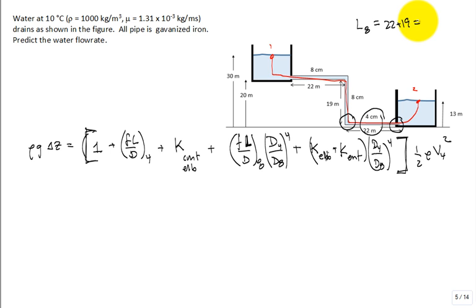Now, what your intuition may be saying, well, I have water in a pipe, and maybe if it's horizontal, I have some air at the top. No, these pipes are full of water, and they're flowing with a turbulent velocity profile. I could see where somebody is like, hold it, something's got to be different. Well, when you're going down, you're changing elevation. Horizontal doesn't change elevation, but that's accounted for in this term over here, what drives the flow, the change in elevation.